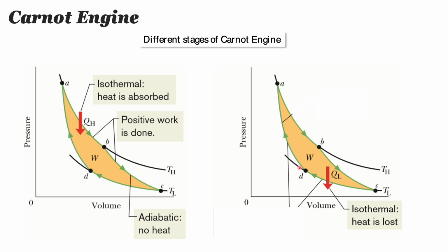The volume has decreased from here to this value, and the pressure from here to almost here, this one on the x-axis. A small change in volume has taken place and a large change in pressure. So the volume is decreased and the pressure is increased, but no transfer of heat has taken place during this process, in going from D to A.